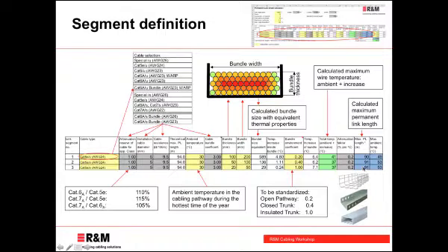Keep in mind, according to standards, the maximum permanent link length is 90 meters. So if you have something that's bigger than that, you just have a reserve. You shouldn't go longer than 90 meters. The last column here is just a calculation of what would be your maximum ambient temperature in order not to exceed the operating temperature, the 60 degrees, for example, for the cable.